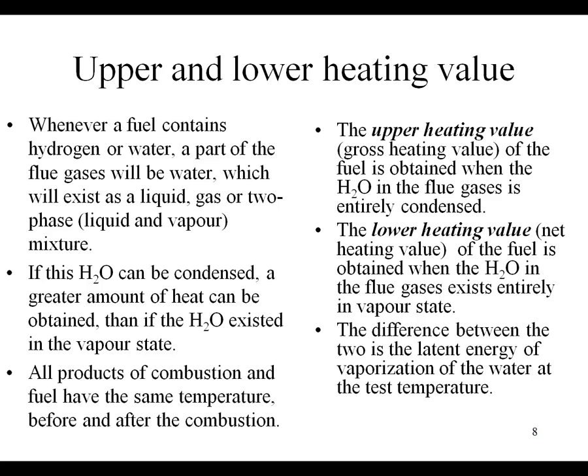So normally, let's take an example, the lignite from Romania. It's a solid coal, and in some situations it contains 70% ash and water. So carbon is about 20%. Meaning in 1 kilogram, you have 700 grams of water and ash, 200 grams of carbon, and the rest is sulfur and oxygen and nitrogen. So you use only 200 grams from 1 kilogram because the rest, 700 grams, is ash and water that you cannot use in the combustion.